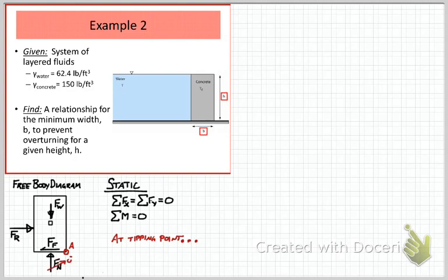Also at that time, the normal force would be 0 because you'd be just beginning to rotate the block up off of the ground, and the friction force would be 0 because it's acting through A with no moment arm, and because you're rotating about point A, not sliding.